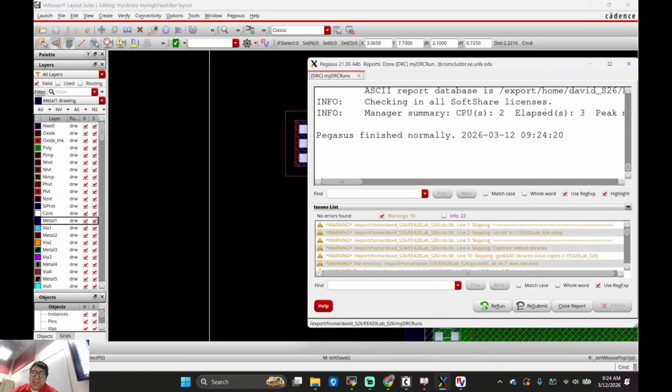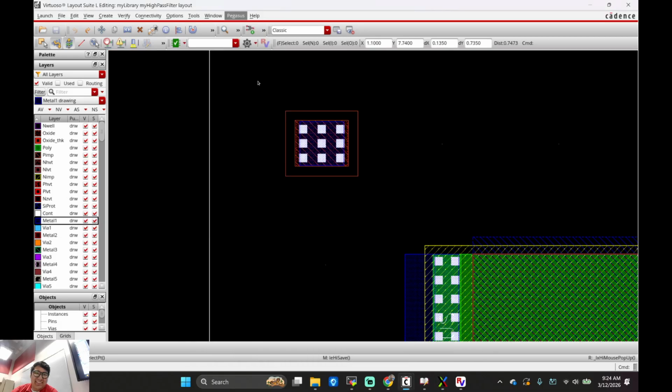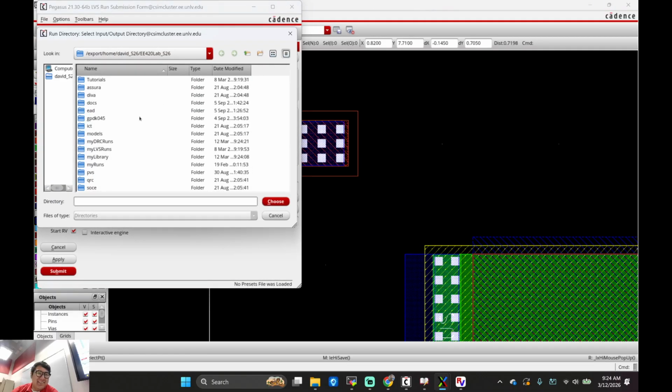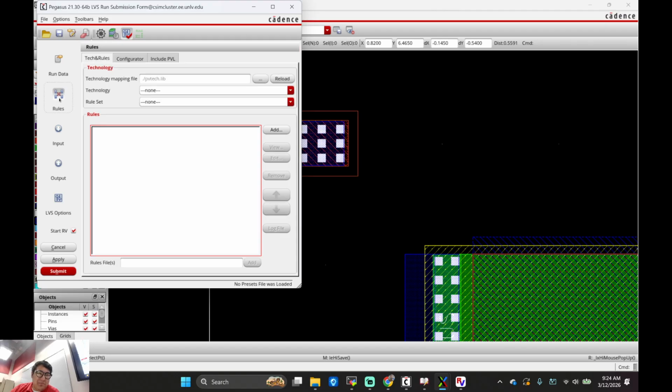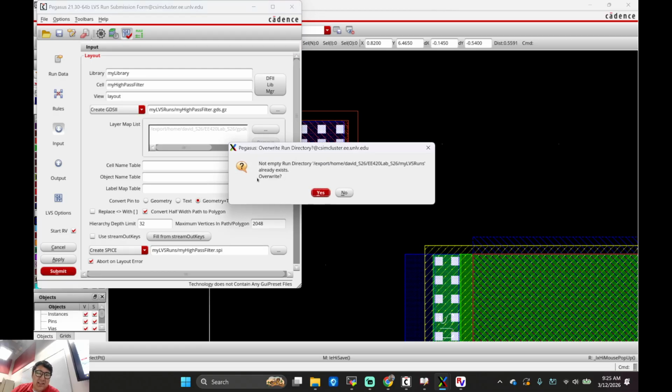Now let's go for your, what do you call it? Your bestie, the LVS. And the LVS, yeah, makes you cry. Okay. If you make a unique folder, my DRC runs, my LVS runs, I'm going to show you what's going on. Hopefully I don't have to, but if you have to, I'll show you what's going on. Let me see there. Okay, set your rules. Don't forget to go to input, change your pins to geometry plus text, submit.